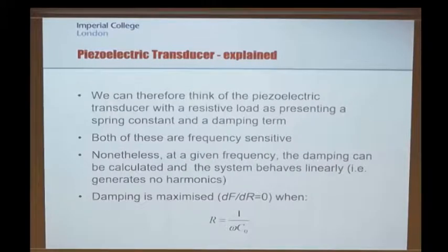Now, at that point, if the force that I need to provide to maximize power generation in a volume is bigger than this force, which is the maximum force that I can provide in my piezoelectric system with a simple resistive load, that's the point where I need to be a bit more clever. I can't just put something onto this that looks like a resistor, or something that mimics the behavior of a resistor. I'm then going to need to put a circuit on there that does something more sophisticated. And that's where you see the sorts of techniques that Michael was talking about yesterday, with these strange shaped waveforms on the piezo, effectively able to increase the damping force on the piezoelectric material beyond what you can get with this simple resistive type load.